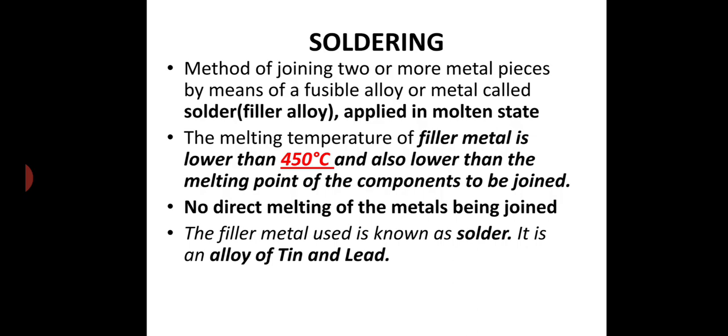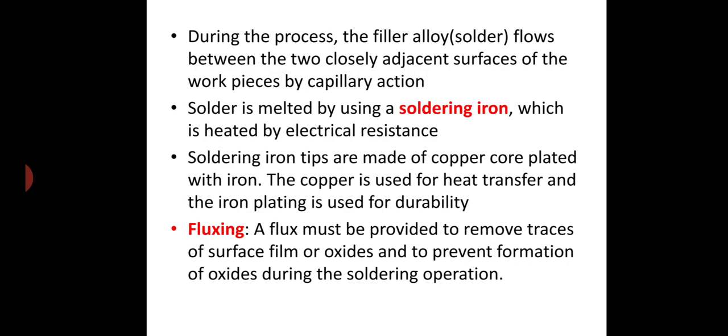You can see the temperature range: the melting temperature of the filler metal will be less than 450 degrees Celsius, and it's also lower than the melting point of the components to be joined. It can be done very simply. Very little skill is required for a soldering process.